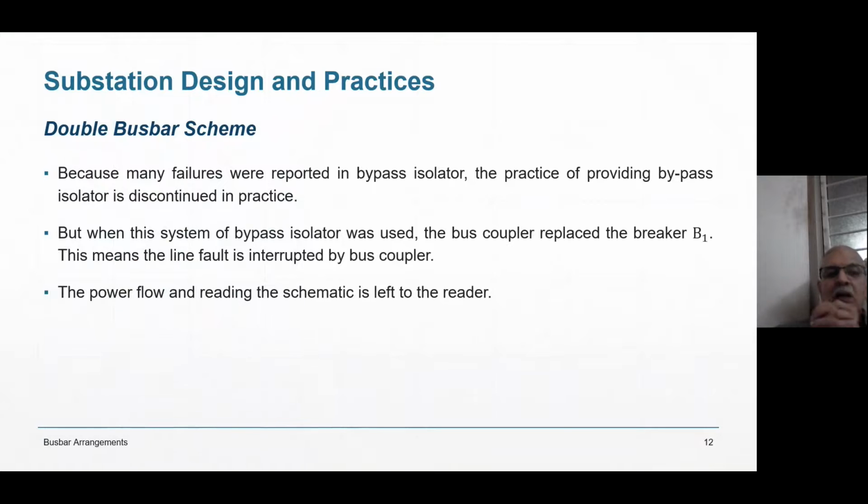So this is the double bus scheme. So we have seen everything, however, we just see through the features of double bus bar scheme. If you see the double bus bar scheme, you will find that there are many disadvantages, but it is not so. The main big advantage is it is highly flexible. You are feeding power to the bus. Even if there is a bus fault, even if you are maintaining the bus, you are not losing power. So the electricity board is not losing revenue also, and the big industries are not losing production also, and people are not feeling discomfort also.